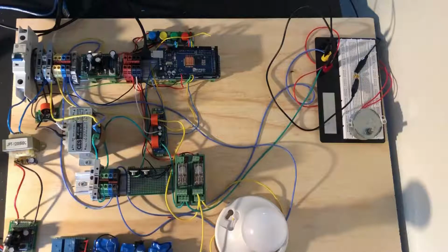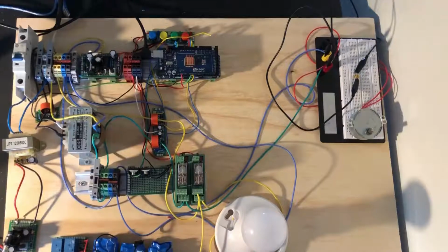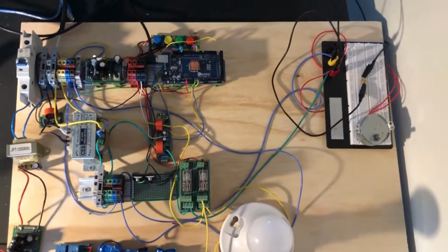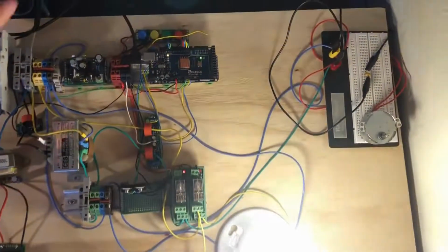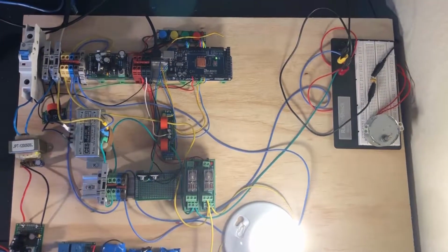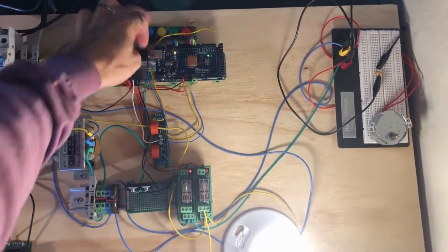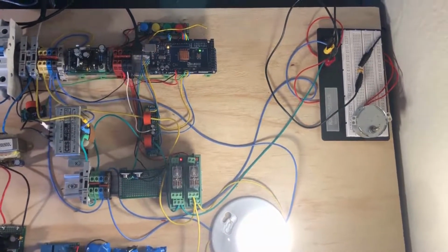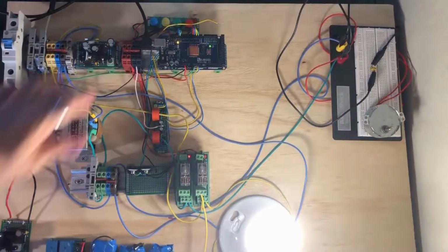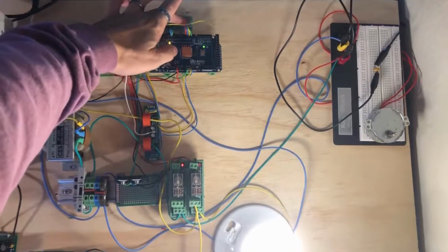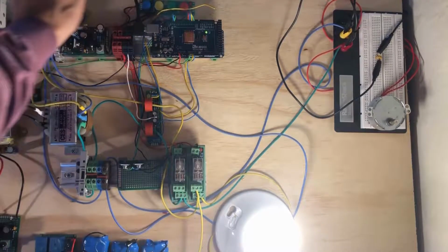Now we can present the entire system working without the microgrid attached. There is a main circuit breaker that we have to turn on. I simulate fault 3 first, which is the industrial load interrupt. We see the motor stop spinning while the residential load stays lit. The relay's red LED indicates this. I want to mention that a MOSFET switching circuit was implemented to energize the relay coils. This was needed as the Arduino cannot supply enough current out of a single pin to energize the relay. Next, I reset the fault, and the motor starts back up.